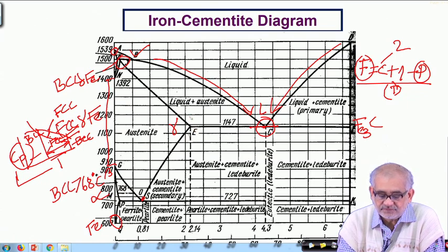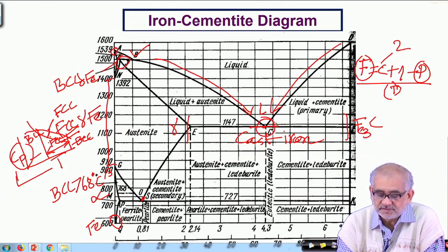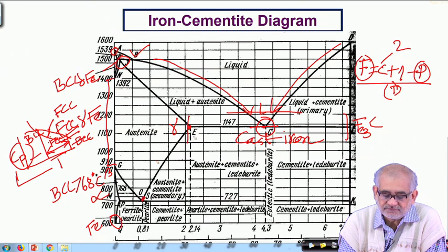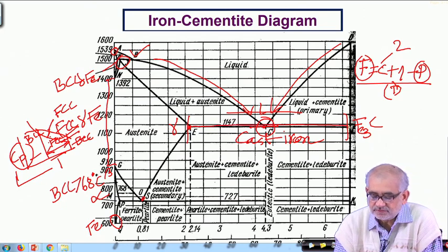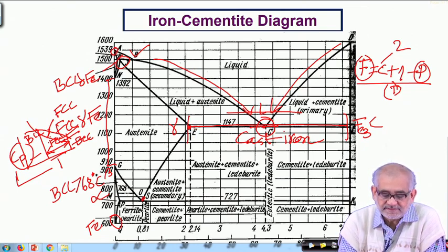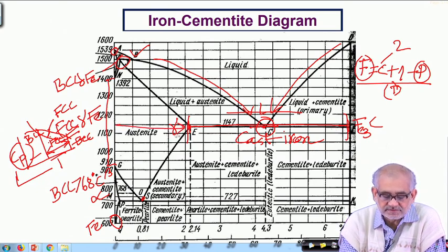So this variety of the iron carbon or iron cementite system is called cast iron, and the name cast iron essentially is derived mainly to signify that casting is very much conducive at these low melting alloys. But the difference between cast iron and steel is not necessarily only in terms of composition, but essentially in terms of this particular horizontal called the eutectic isotherm. So any composition which intersects this eutectic isotherm is called cast iron, and the remaining are essentially called steel.